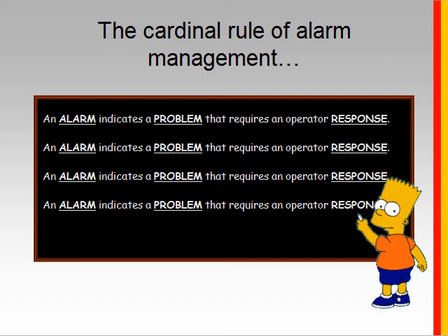The corollary to that is if you walk into the control room and you see that there's an alarm on the console and the operator is not responding to it because nothing really happens or nothing really goes wrong, then that point should not be an alarm. And this basic philosophy of what an alarm means and what should happen is really a guiding principle that we use throughout alarm management. And we hold up this principle throughout the phases, the stages of the alarm life cycle to make sure that we're doing the right thing.